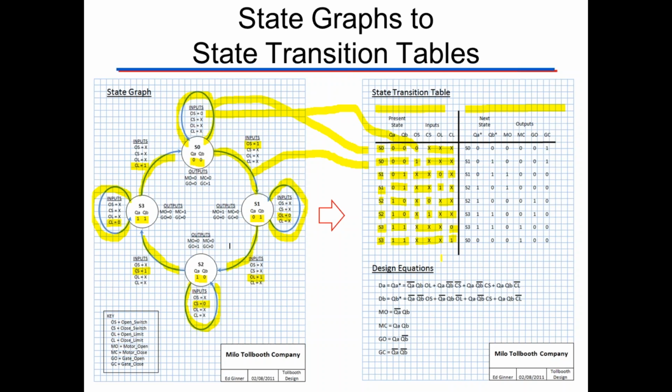And now this is what makes the state machine work. If we go to our output side, we have these 2 columns here labeled next state. And the little stars here mean next state of the flip-flops. So the first row here is basically the outputs of state 0 right here in the idle mode. So we can copy this information right here.